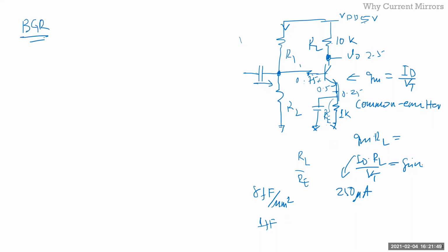Or it could be just a simple circuit as a VT over R, okay? But this is a big, huge circuit, okay? So let's say a band gap circuit could be as big as like 200 micron by 100 micron, okay? But it gives you a nice current source, okay? If you design it well, it'll give you a nice current source. But I need now thousands of those things copied, right?